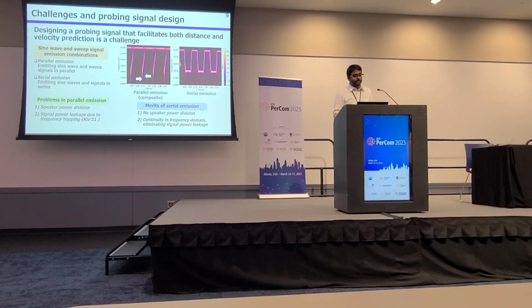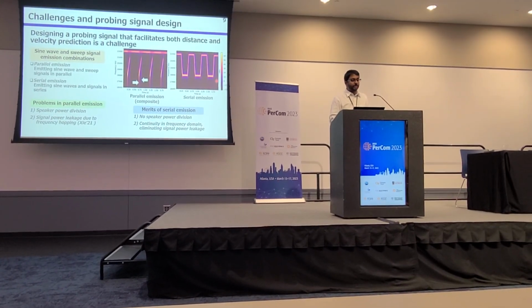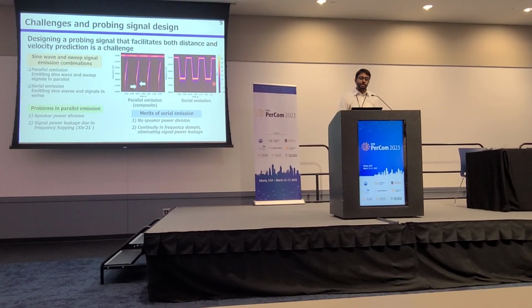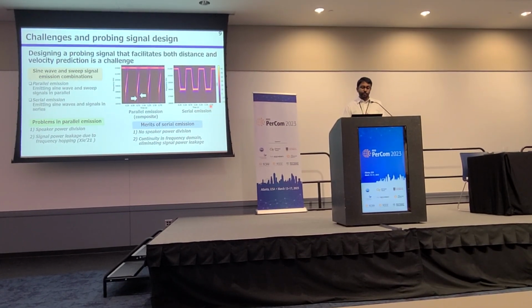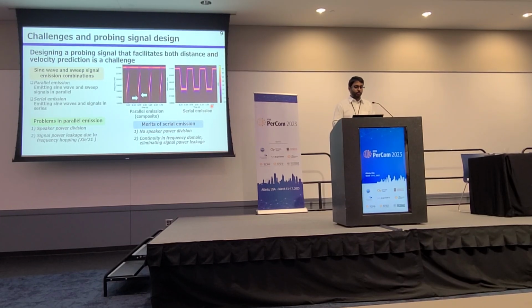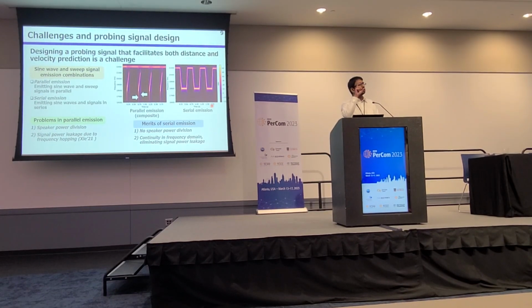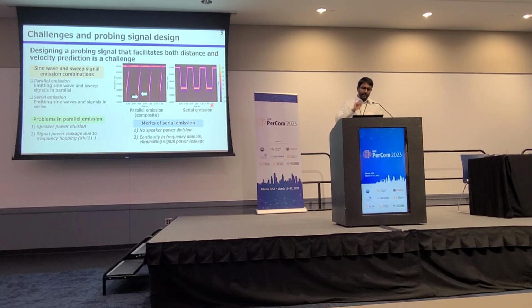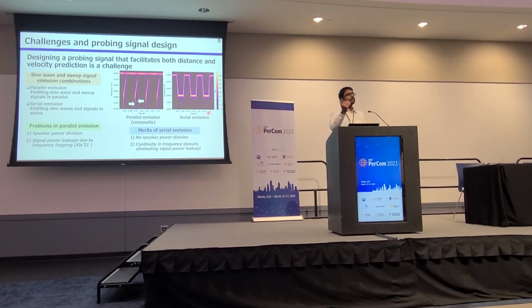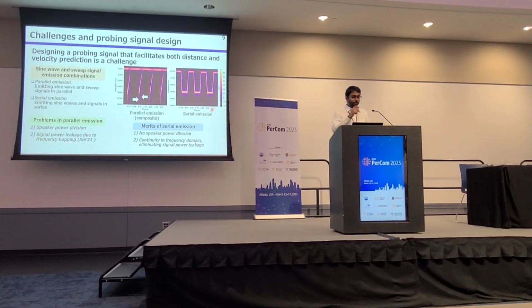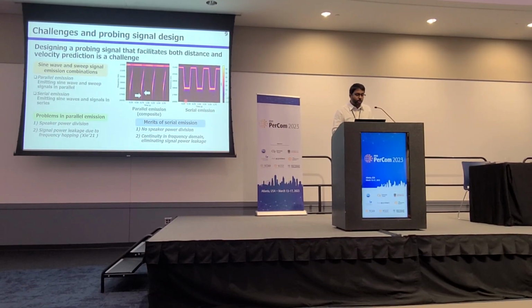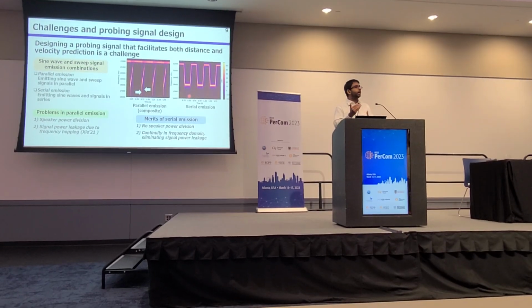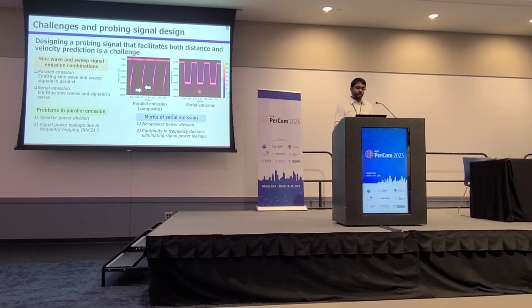Therefore, we came up with this second design where we serially emit sine wave segments as well as sweeps and inverse sweeps. And here we do not have the speaker power division problem, as we only emit a single signal component from the speaker at a time. And as the signal is continuous in the frequency domain, it eliminates the signal power leakage problem as well. As you can see, there are no noises jumping into the audible range of human beings. So for future experiments, we use this particular signal design.